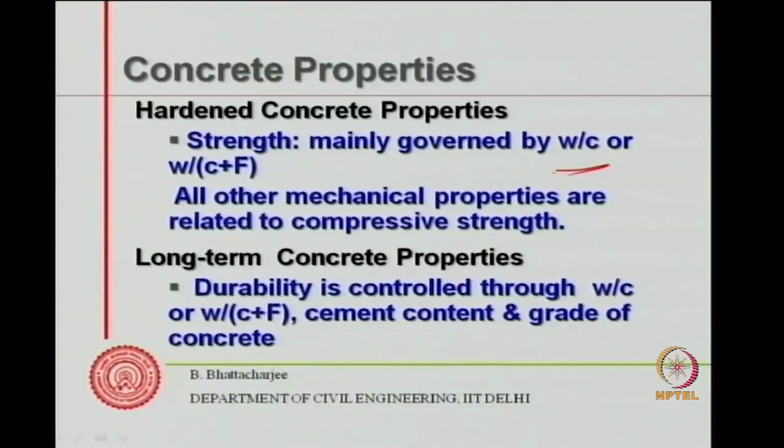Higher water cement ratio means more capillary pores. Therefore, strength of the concrete, which is a function of the porosity and pore sizes, is governed by water cement ratio. We shall see this in detail when we talk of the factors affecting strength of concrete.